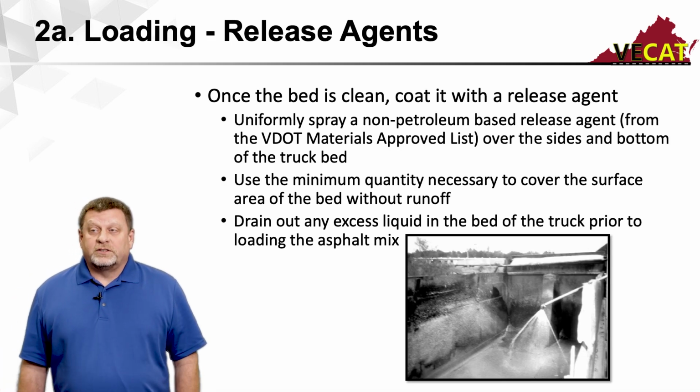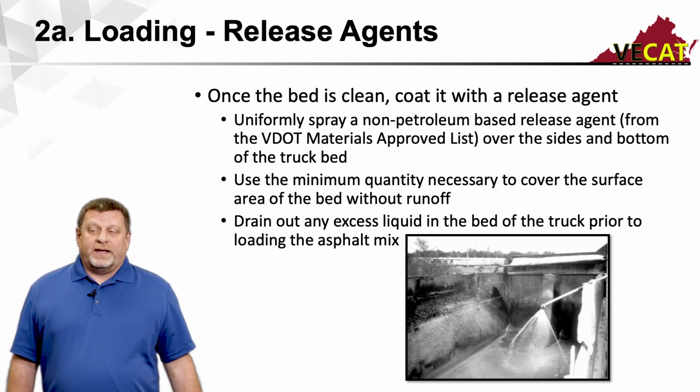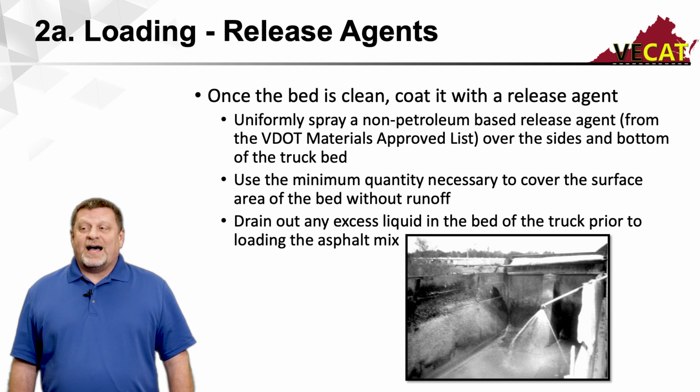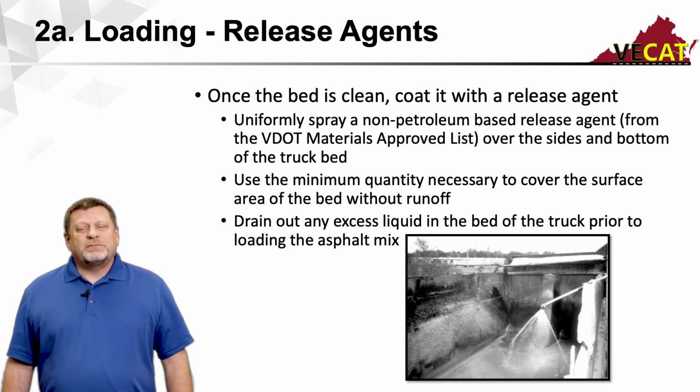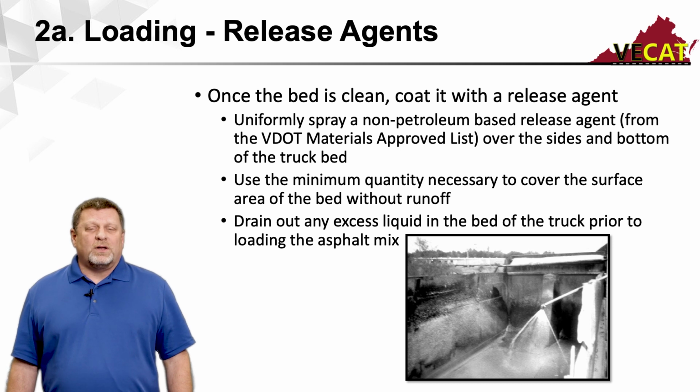Continuing with loading, here's the release agent I was talking about. VDOT has an approved list, so you have to use a material that's on the VDOT approved list. And once the truck bed has been cleaned, you want to spray the sides and the bed of the truck. But you have to be careful. You don't want to put too much extra material in here. You don't want a lot of puddling or ponding in the bed of the truck.